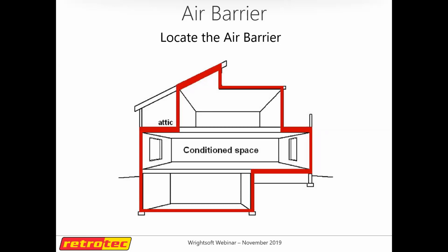I might have to start stealing that. The question whether or not I should consider the basement conditioned space is always a tricky one to answer. Maybe I'll just start putting them toward wherever your air barrier is. That's your conditioned envelope. Exactly. It's usually what we end up doing anyway. And the way ResNet says it too, if it's conditioned space, if it's being served, then yes, you absolutely have to include it. Otherwise, the air barrier is at the floor.